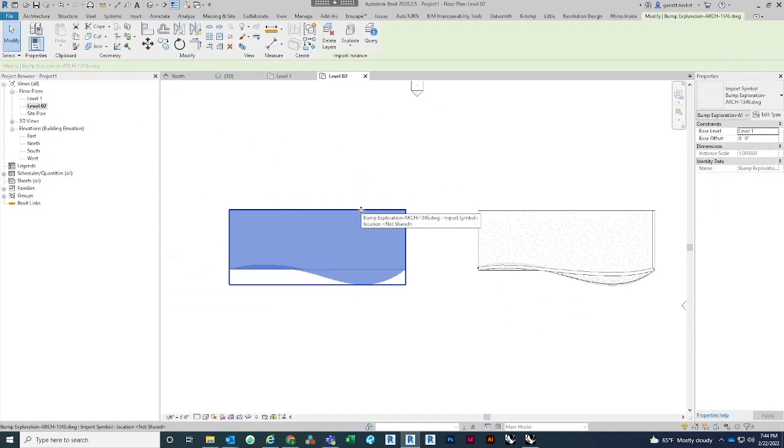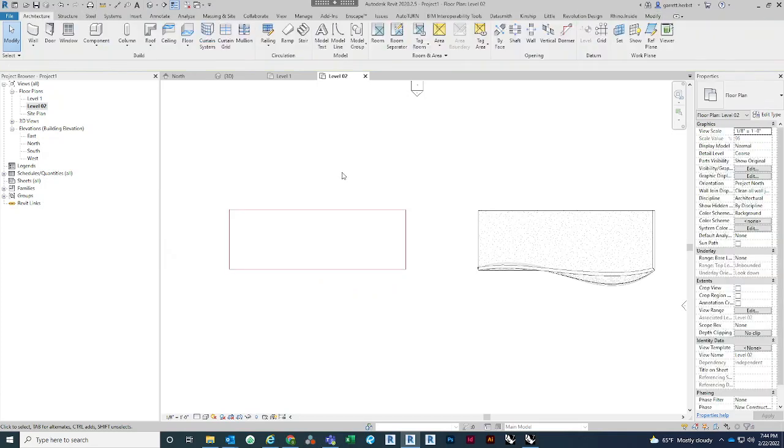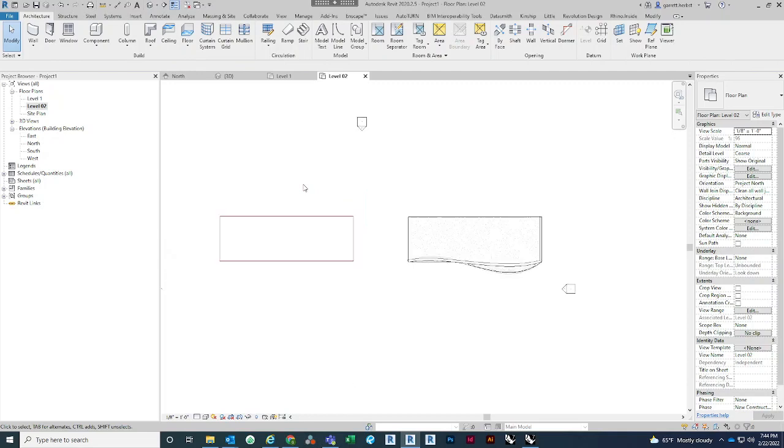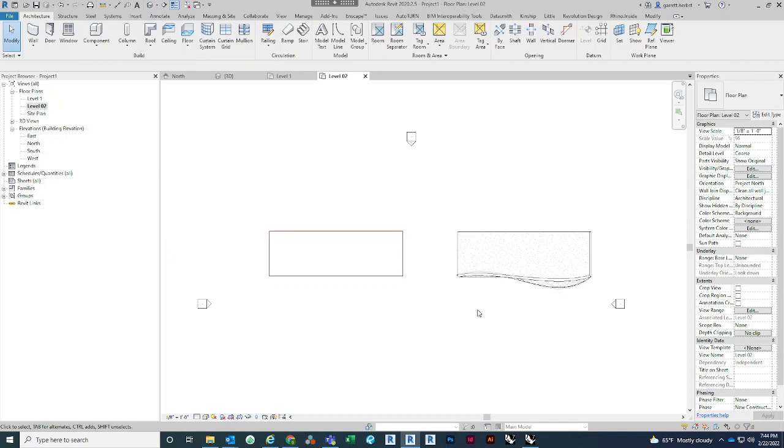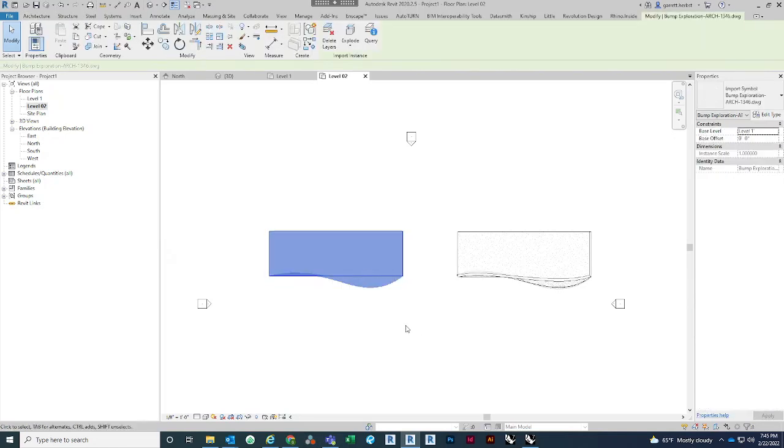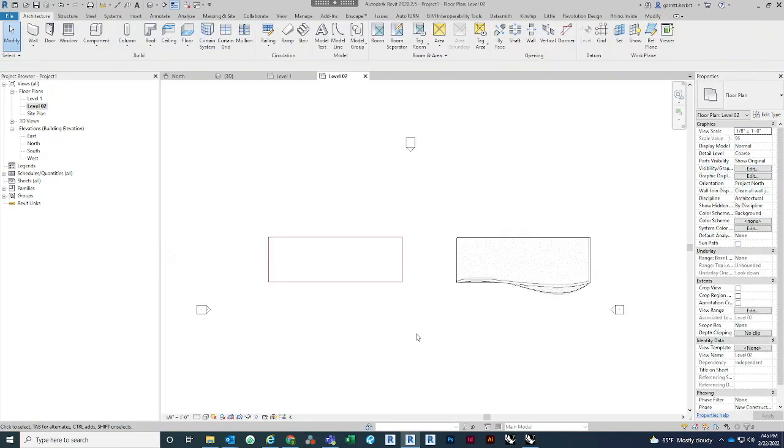When you directly import a file directly into the base Revit environment, it doesn't cut the geometry. It's weird, I'll just be frank, it's weird. So if you're banking on it cutting through and you don't plan on using a conceptual mass, like let's say you have a piece of furniture or an object that you don't need to manipulate or apply any Revit elements to, but you want it to cut and look correct.